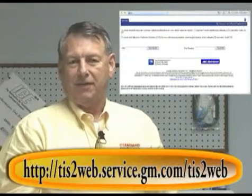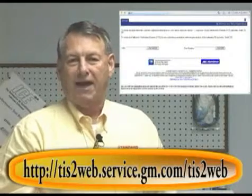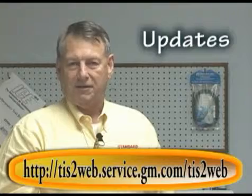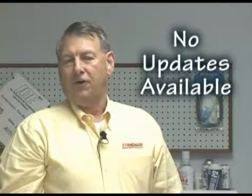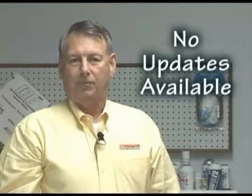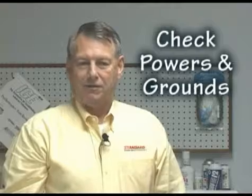The next step in our diagnosis will be to go to GM's TIS2 website to search for reprogramming updates for the PCM, the BCM, as well as the HVAC control module. Our step confirms that there are no updates that may affect no blower operation. Therefore, we will approach it from our traditional diagnostic standpoint. We will check power and ground circuits.